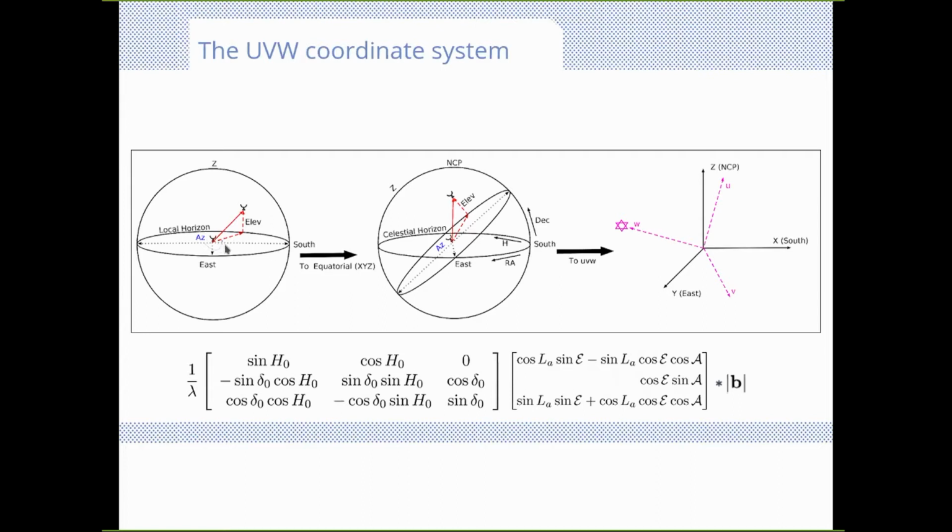So let's say you have 2 points on a big aperture, or equivalently, as we'll see in this lecture, 2 different antennas. Then we can define a vector between those 2 points. So let's call that a baseline. And that baseline is fully defined by an azimuth angle to the projected component onto the local horizon of the observer, and an elevation angle along the great circle up to the zenith position here, directly overhead. Now, the azimuth angle is always going to be defined north through east, right?